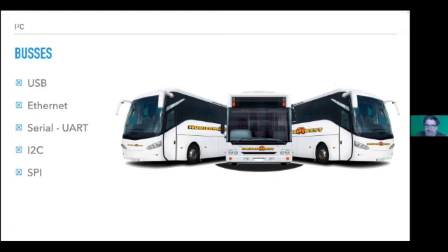And then what SPI also has is that now, if I have a lot of different devices on my bus, which one do I want to talk to? So then I have a pin that I put high, give a signal and say, I want to talk to that weather chip. But if I have to signal that with one pin, then every time I have another sensor, I need one more pin.